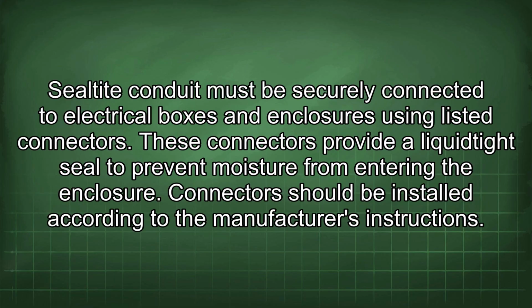Sealtite conduit must be securely connected to electrical boxes and enclosures using listed connectors. These connectors provide a liquid-tight seal to prevent moisture from entering the enclosure. Connectors should be installed according to the manufacturer's instructions.